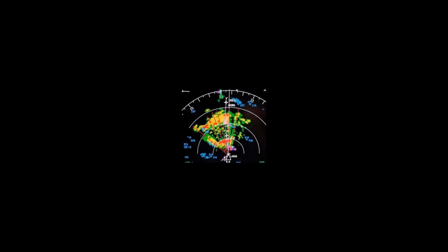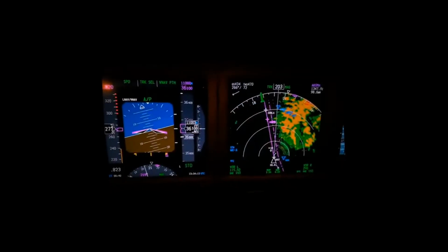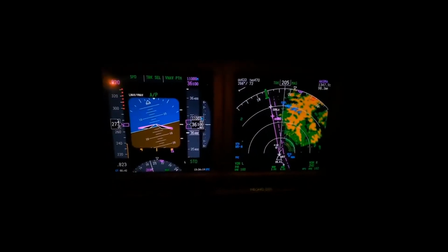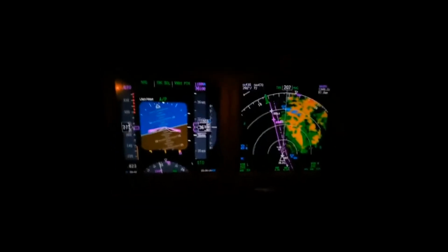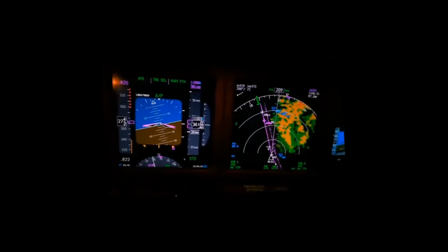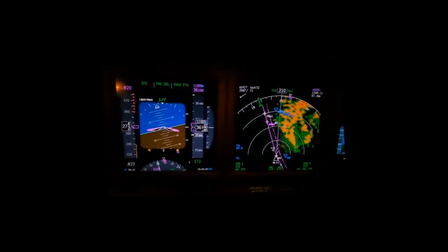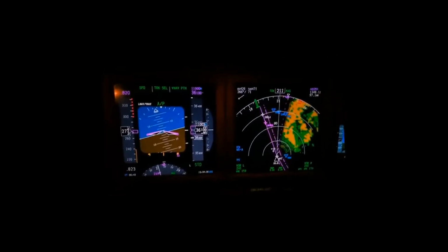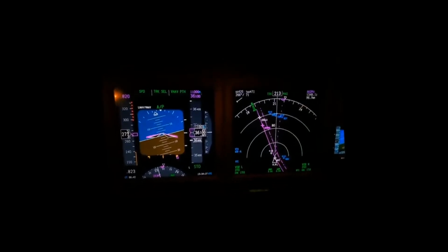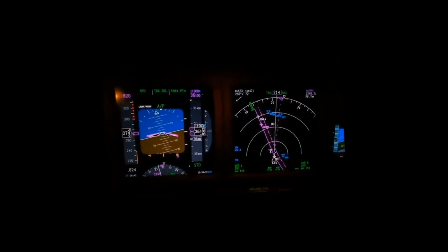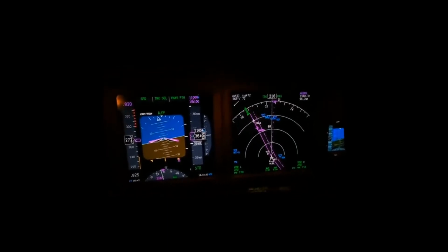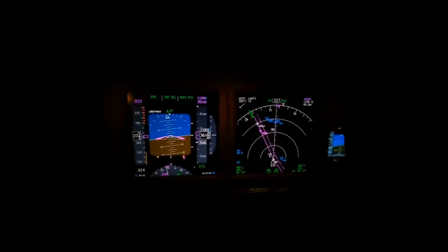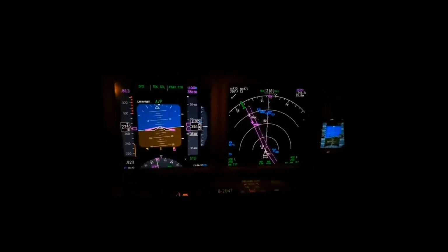Radar systems come into our shop with write-ups regarding spoking as the reason for removal off the aircraft. The most common type of radar spoking appears on the display as a pie-shaped patch only when there's weather. Spoking is a general term used when a radar system fails. You can determine which part of the system is causing the problem based on what appears on the radar display. This occurs when the receiver and transmitter lose lock and do not track with each other.